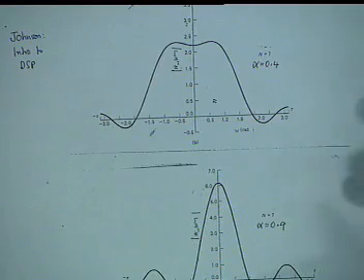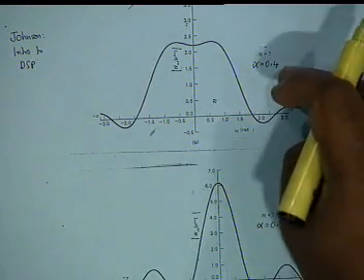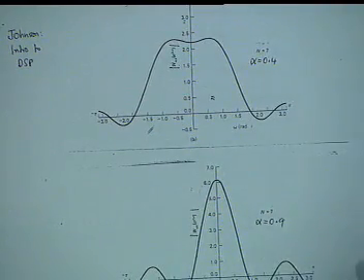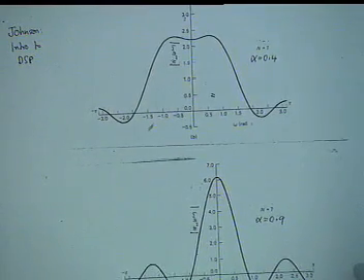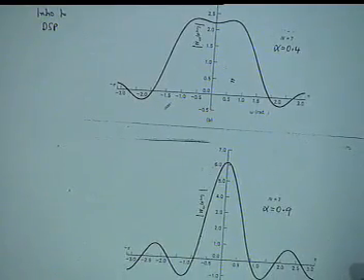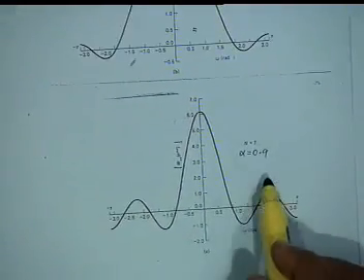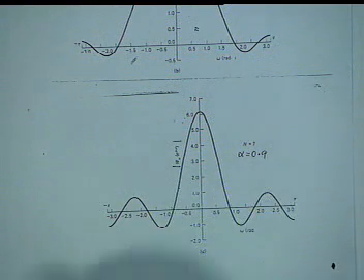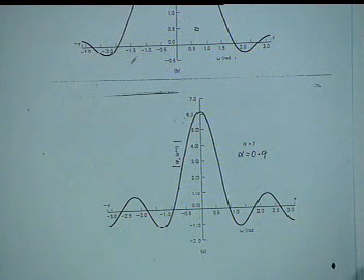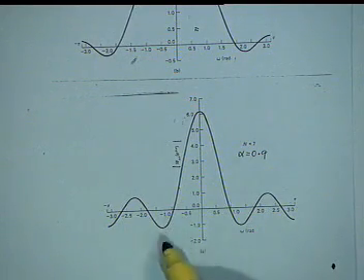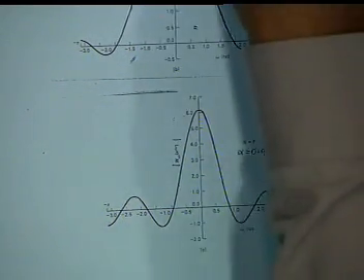As you know, alpha equal to 0.5, there is no dip, it is a cosine wave. So alpha equal to 0.4, there is still a dip, but a smaller amplitude, and when alpha increases beyond 0.5 and higher, there is no dip, there is only one main lobe, and this is the story for alpha equal to 0.9, considerably higher than the value used by Hamming. And once again the same phenomenon, the main lobe width decreases, but the side lobe height increases.